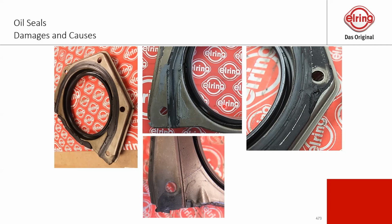So there are some defined spots where it's recommended to use it. This is underneath where the oil pan is, but also check the quantity. This is quite too much where they used it, like here, because there's also a high risk that something gets into the sealing line of our oil seal. This is also what you should avoid. So this is really a critical point. This is very important to mention to you.